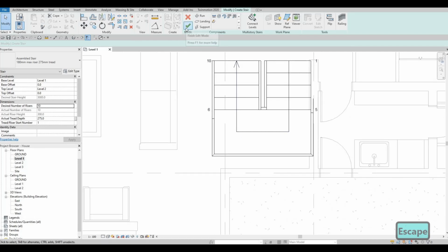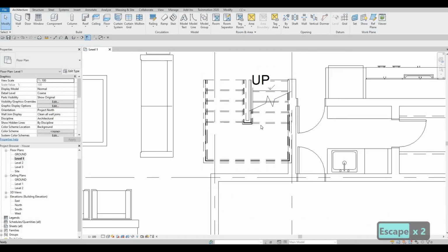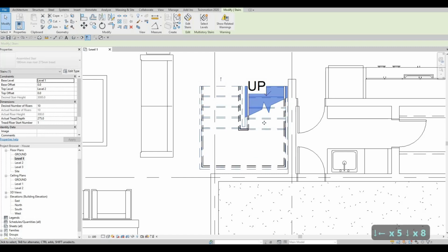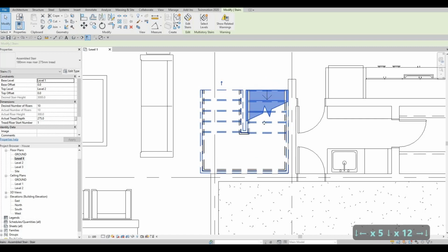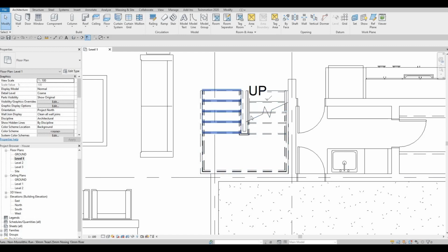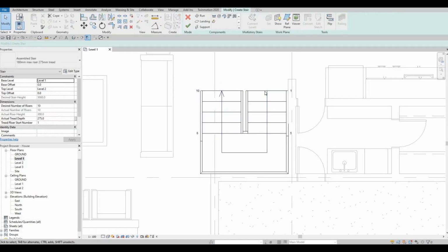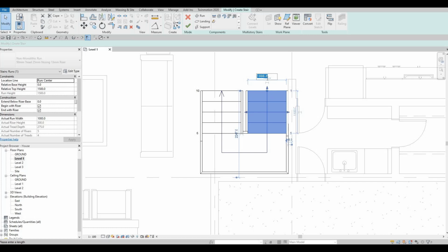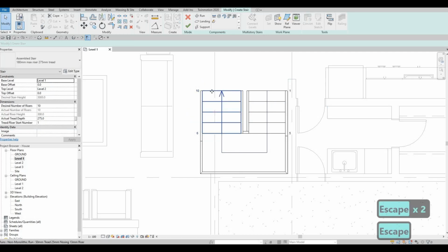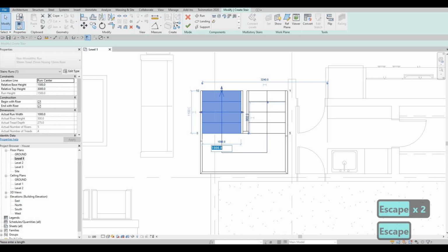What I usually do is click on finish first. Once I click on finish, I then do what I need to do, like moving it to the corner, and then now we just need to edit so that it's snug around here, so it's not showing. So here I'm going to edit this again, select that, edit stairs. Now instead of 1000, around maybe 950, so that we could have the gap. This one as well, we need 950, so here 950.